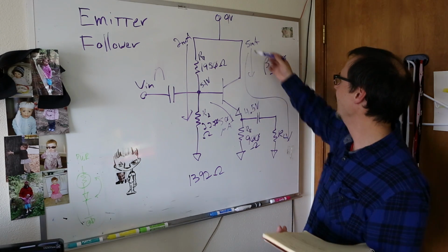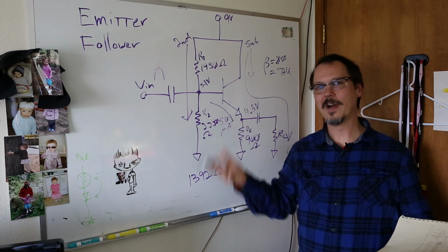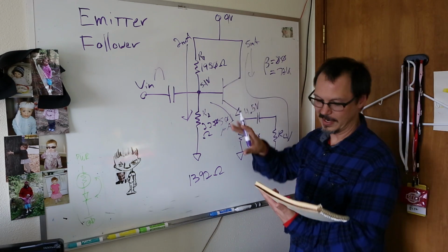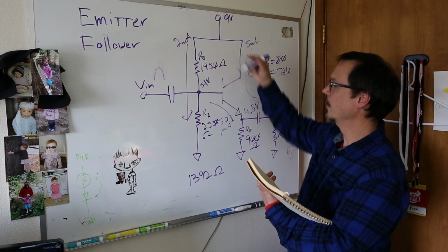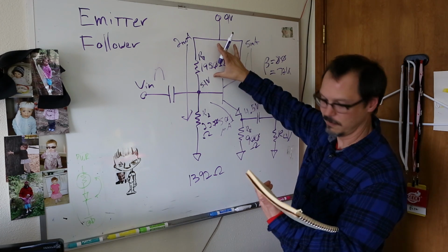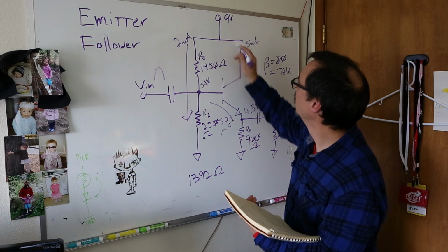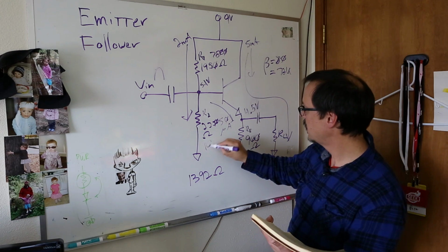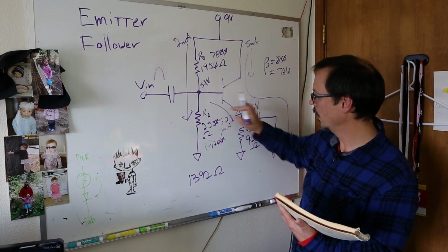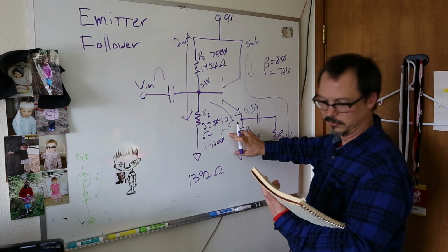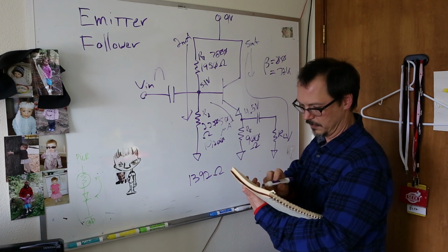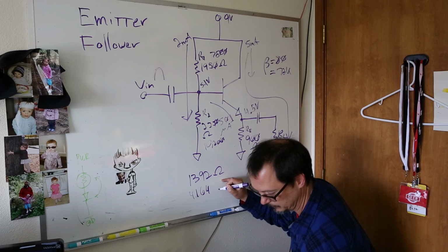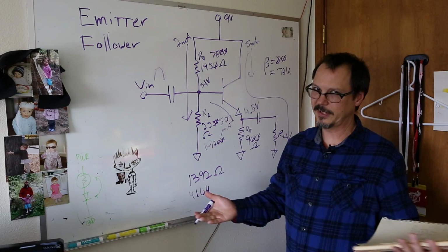A factor of 10 on that would bring me down, like I said, to 500 microamps, which is much better. In fact, I recalculated all of that, and if you assume this is 500 microamps, these numbers change to 7,800 for that guy, and 10,200 for R2, and so your parallel input impedance becomes 4164. So it's about a factor of 3 better.